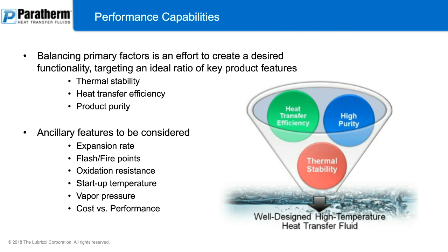One that's a real headache for a lot of professionals in the thermal fluid range is flash and fire points. I just want to make a kind of a public service announcement here. The majority of thermal fluid systems are going to run well above the flash or fire point of the selected fluid. I would consider flash and fire points mostly for storage and shipping capability of the fluid and not so much for the actual operating limitations. If there are any questions based off of that, try to catch us during the question and answer session on why that's the case. But I would not use flash and fire point as a primary consideration for choosing one fluid versus another. You can get yourself into some real headaches and complexities there by doing that.